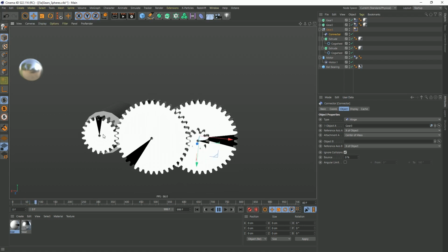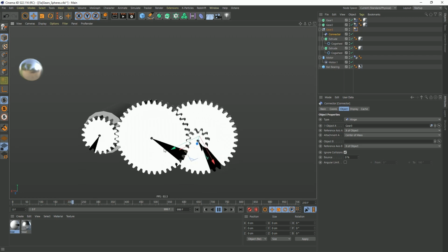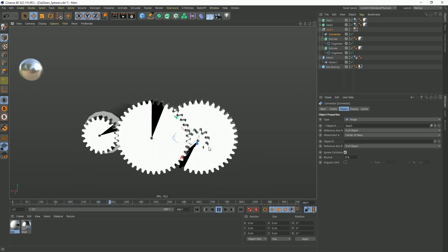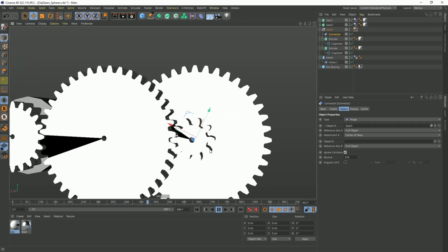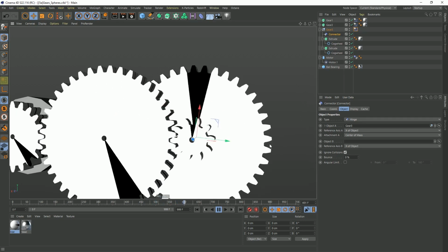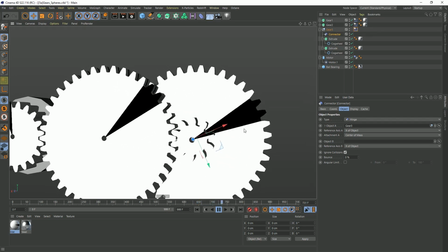Now we have this gear translating into this one, and that one's translating the small one, which is then making the big one spin. Now, even though these are both spinning at the same speed, a lot fewer teeth are passing by as this little one rotates. You can see that we kind of get 1, 2, 3, 4, 5 teeth going by. Over here, it's like 1, 2, 3, 4, 5, 6, so many teeth are going by. So we've actually increased the speed of our overall setup.